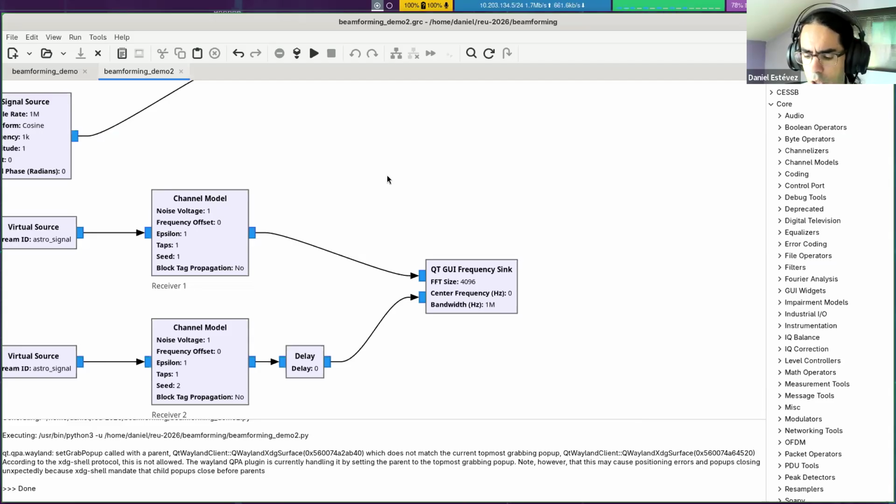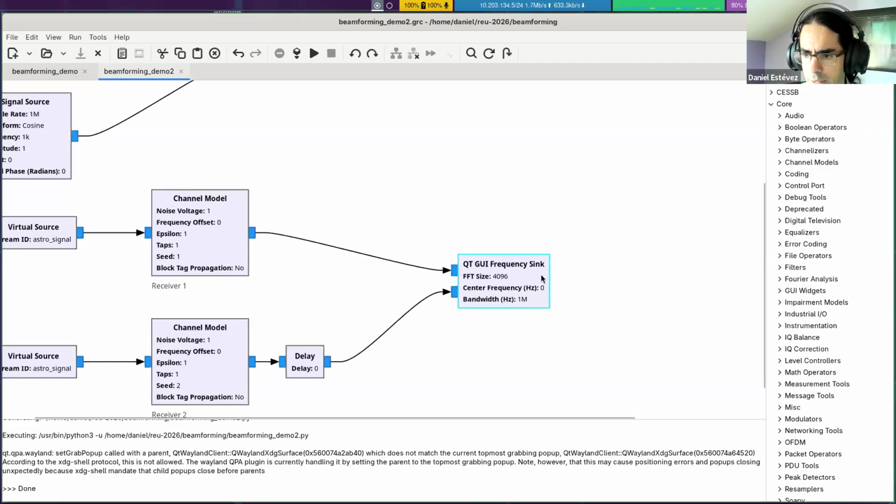So then you can imagine if we have larger antennas, we can collect more of that power because we have more collecting area. And another idea we might apply is to have multiple antennas, because that amounts to more collecting area if we sum the collecting area of all the antennas. But then what to do, because each of the separate antennas has a separate receiver. Basically here we are simulating two antennas with one receiver each. We want to combine the signals somehow so that the power is combined.